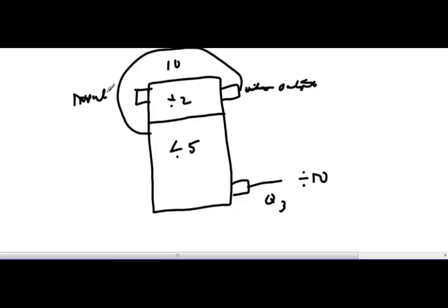And you say, wait a minute, if I have a counter, how come it's a divide by counter? That doesn't make any sense. Who made up this stuff anyway? But I could do that. And then I'd have another guy here, Q2, and another guy, Q1, and this guy here would be Q0 because he's the top guy. And Q2 would give me divide by 8. And this would give me divide by 4.